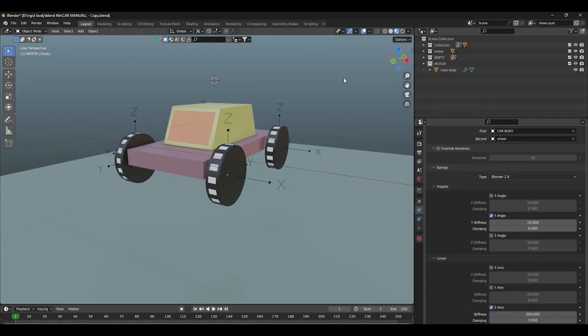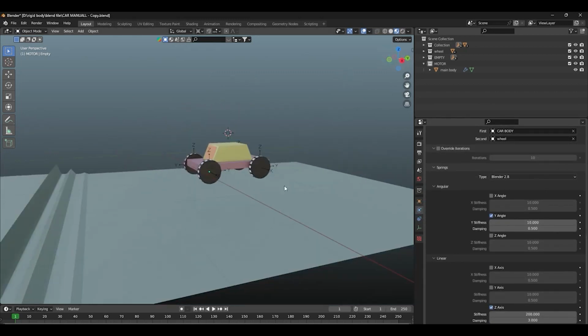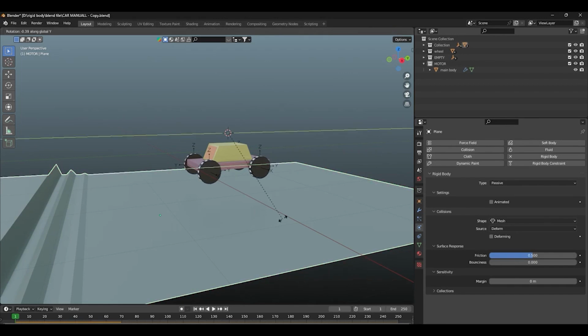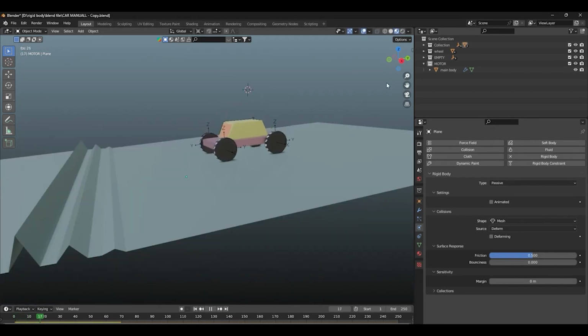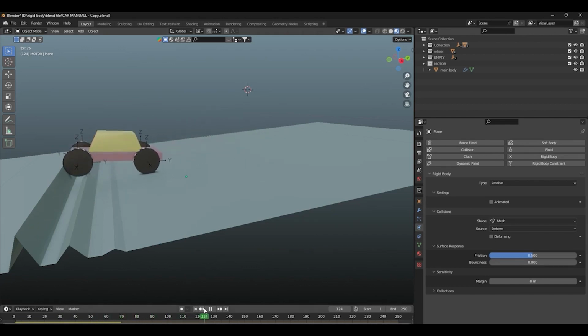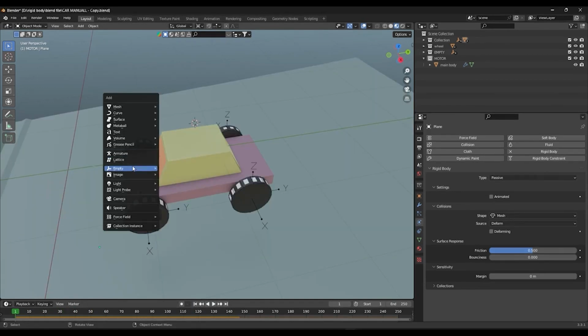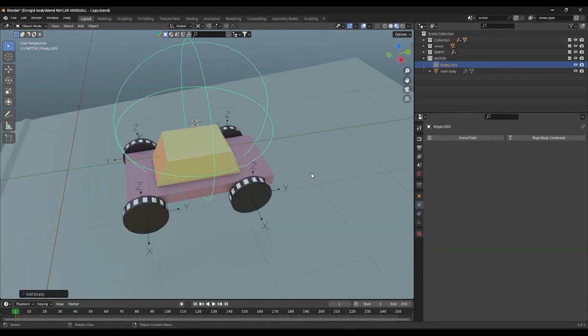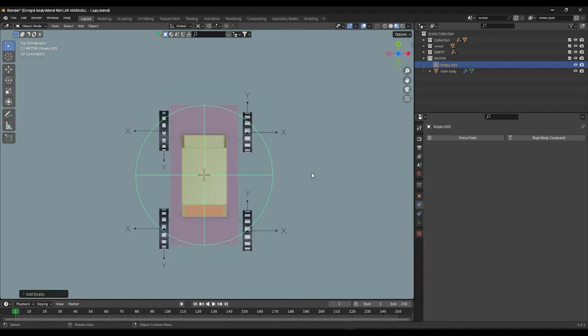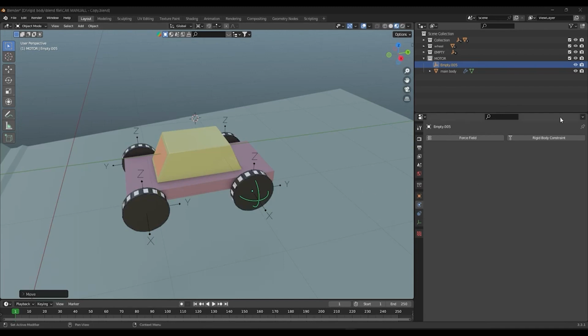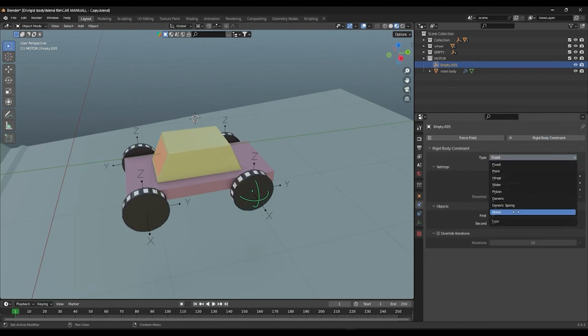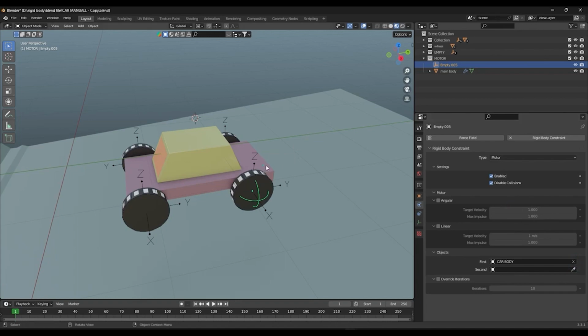Now, if you keep an inclined surface with some hurdle on the road, the car assembly will react to it, but the wheel movement is not sufficient or natural. So, we need to add a motor constraint. To add a motor, insert a sphere empty. Reposition it to the tire, then in rigid body constraint, select motor. Select the first object as the base body and second the wheel.